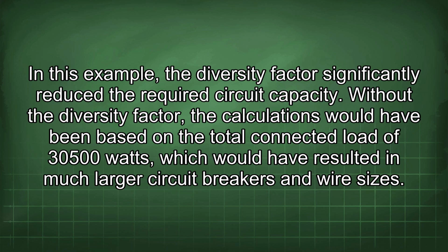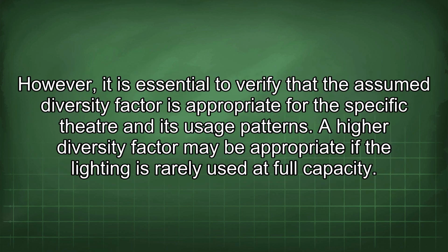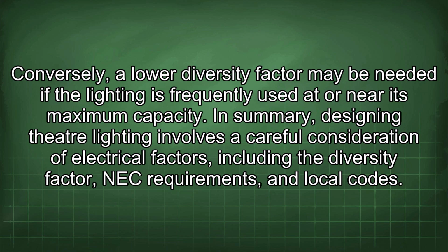In this example, the diversity factor significantly reduced the required circuit capacity. Without the diversity factor, the calculations would have been based on the total connected load of 30,500 watts, which would have resulted in much larger circuit breakers and wire sizes. However, it is essential to verify that the assumed diversity factor is appropriate for the specific theatre and its usage patterns. A higher diversity factor may be appropriate if the lighting is rarely used at full capacity. Conversely, a low diversity factor may be needed if the lighting is frequently used at or near its maximum capacity.